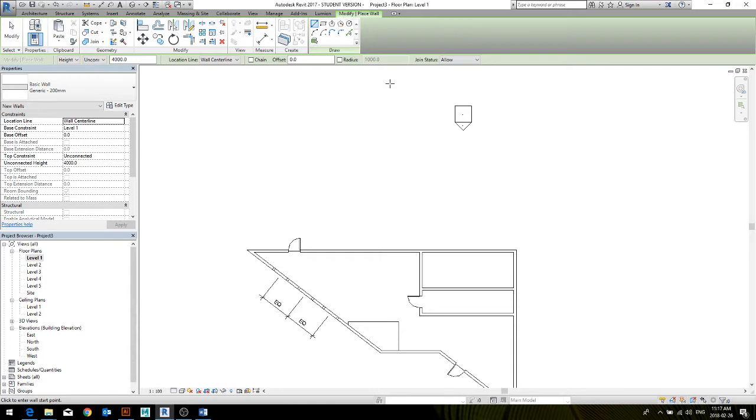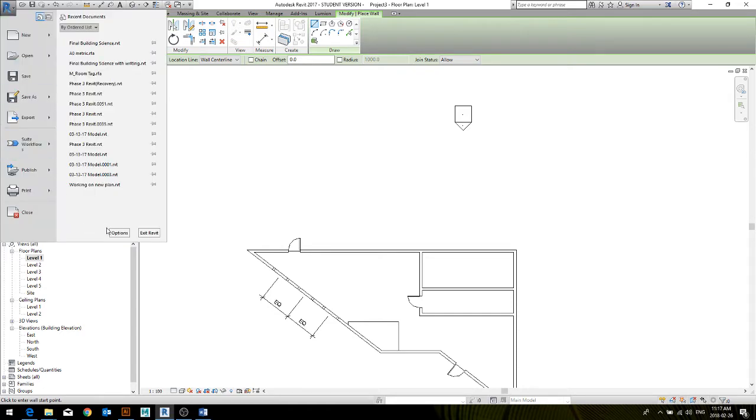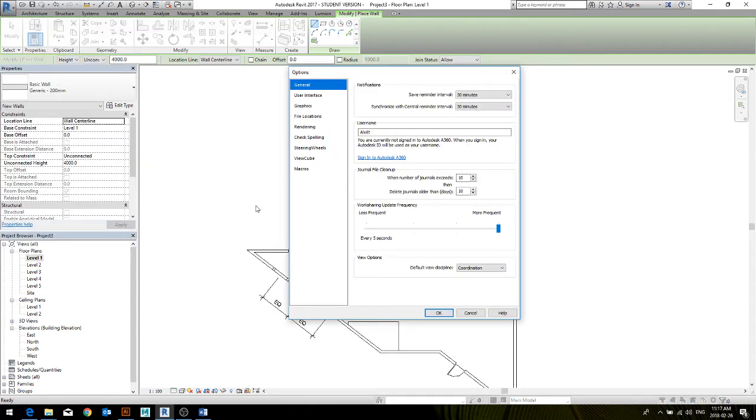Well, the way Revit saves, it'll always overwrite your file and just save a new version and keep it in the same folder that you keep your Revit file in. And you can tweak how many versions your file will save. I've had it before where I've saved like 100 versions of my file and it'll take up so much room on my computer.